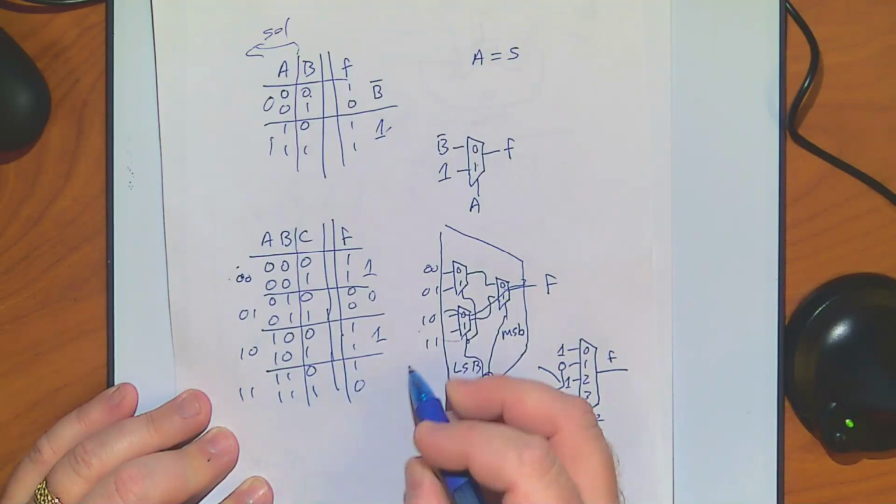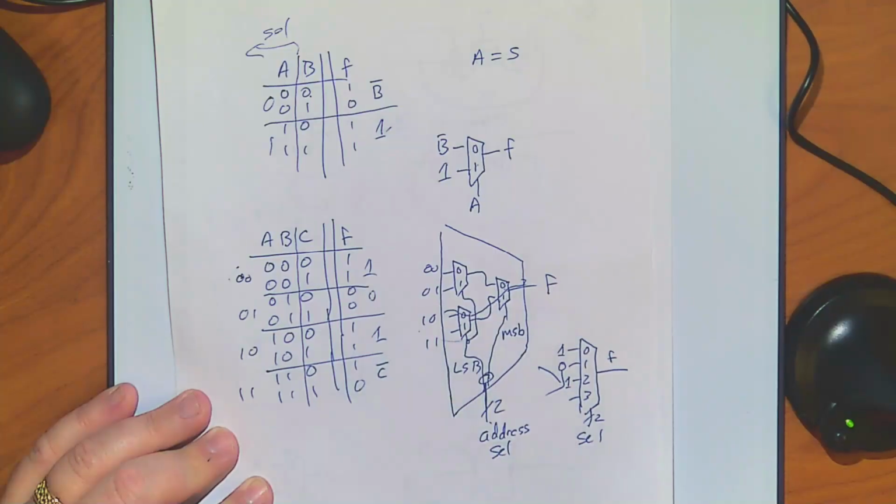1, 0 is the flip of this, so that's C bar. So I'm going to put a C bar on 1, 1, or 3's. There you go. Instant gate built to implement that logic function you came up with randomly. We did that in like 2-3 minutes with me making commentary. See how elegant it is once you have these transmission gates? It's a surprisingly neat technique.